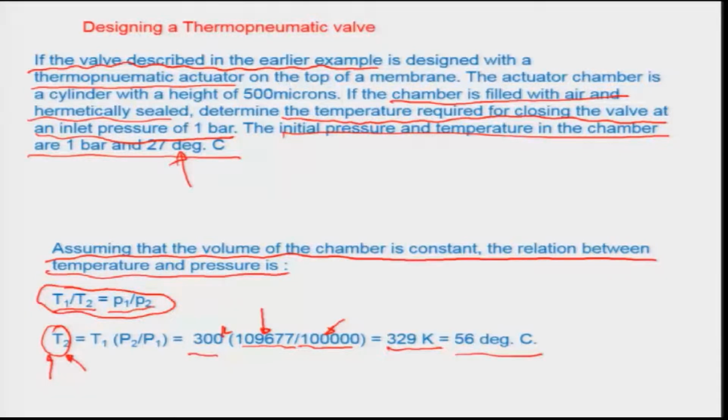We would now like to design another actuator, an electrochemical actuator, which would play the role of an electrochemical microvalve. Of particular importance for me to tell you is that such valves are very commonly available within microflows and microfluidic systems, because they are typically electrically driven, and it is always better from an integration possibility into a chip scale, a microchip scale. So, this is what we want to do here.